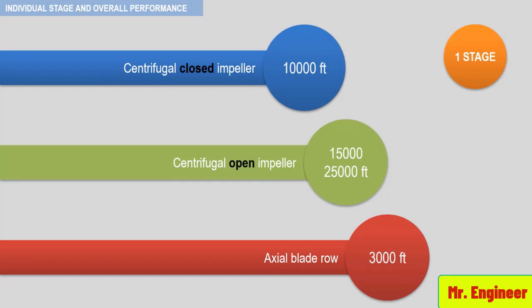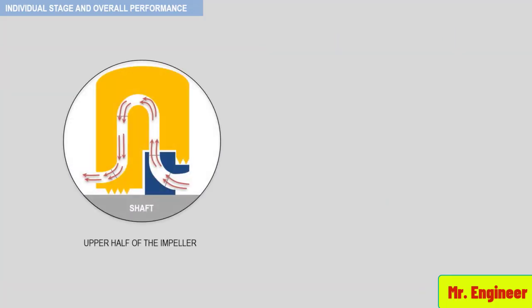The following figure shows, as a reminder, the components associated with one stage of a centrifugal closed impeller. Recall, we have seen this in detail in a previous section. A typical stage consists of an impeller, stage seals, namely the eye seal and the shaft seal, a diffuser, a crossover, and return passage or inlet to the succeeding stage.